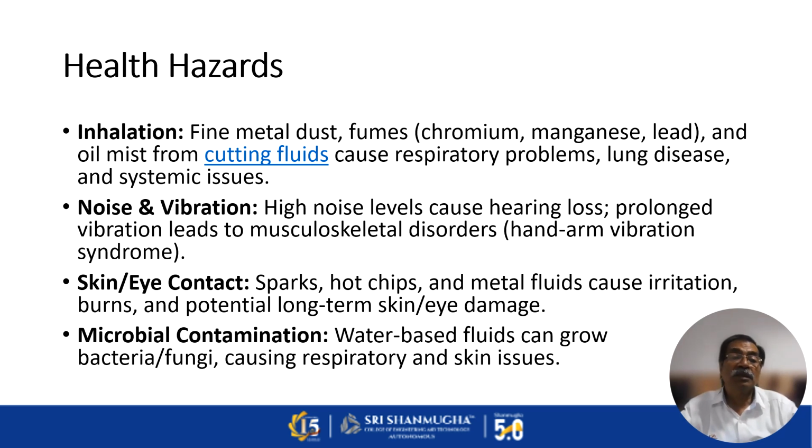Health hazards. Next, we'll see what the health hazards are. Inhalation: fine metal dust, fumes like chromium, manganese, lead, and oil mist from cutting fluids cause respiratory problems, lung diseases, and systemic issues. Then noise and vibration: high noise levels cause hearing loss, and prolonged vibration leads to musculoskeletal disorders, that is hand-arm vibration syndrome. Then skin and eye contact: sparks, hot chips, and metal fluids cause irritation, burns, and potential long-term skin and eye damage. Then microbial contamination: water-based fluids can grow bacteria and fungi, causing respiratory and skin issues.